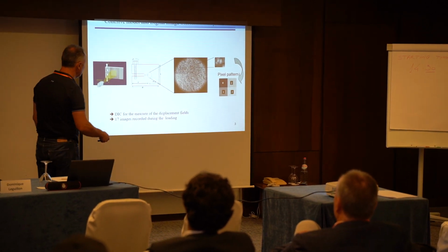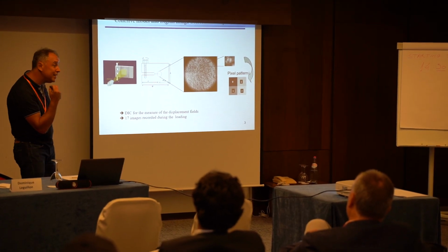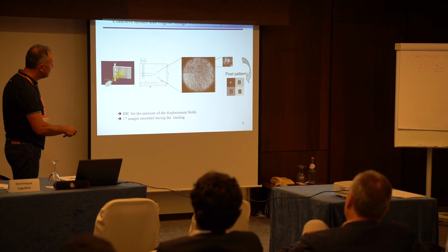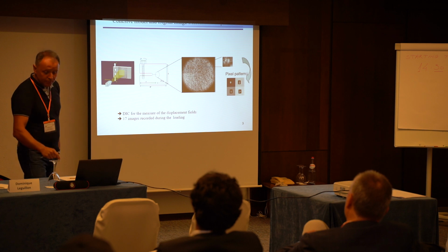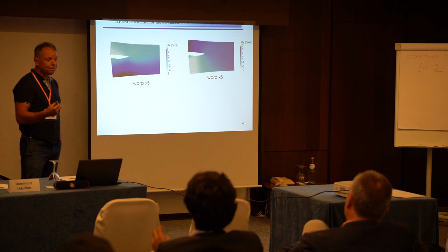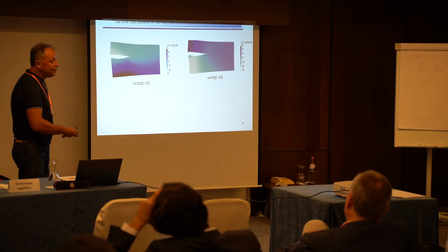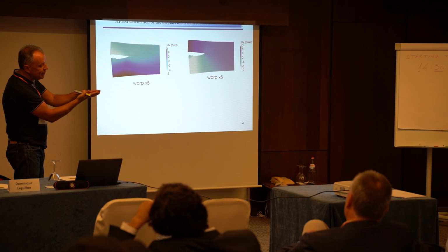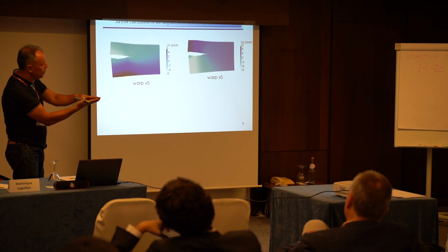So in the past, I've been working with, for instance, Julien Rotoré. We had been machining a natural crack, which is not trivial in a single sample, and doing micro-scale digital image correlation. We were loading, for instance, a sample of PMMA like this. The crack is here. We captured the displacement field around it, and the idea was then to try to identify the cohesive model for the failure mechanism in this material. The cohesive model is very simple when we present it. It's the traction separation law that precedes the crack nucleation.